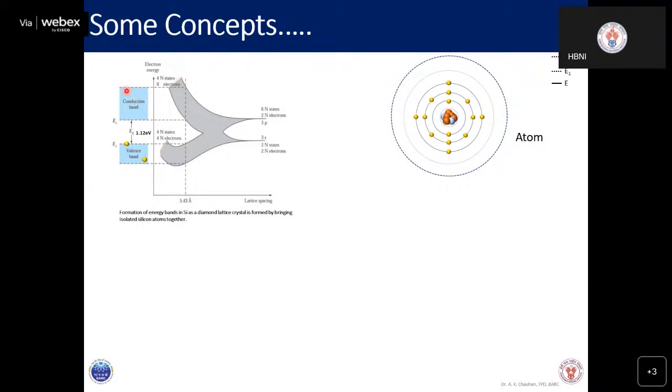So what we see here is the conduction band, and the valence band corresponds to this line here. If we can somehow compress the entire lattice to further reduce this spacing to 5.2 or somewhere here, then the conduction band will move upward, and the valence band will come down, so the gap will increase.